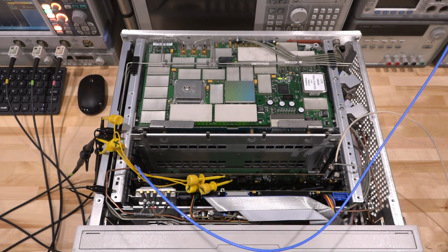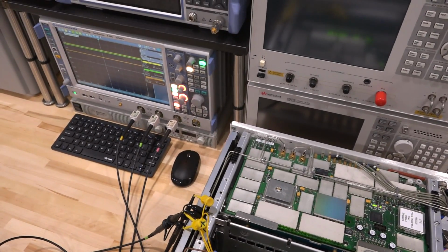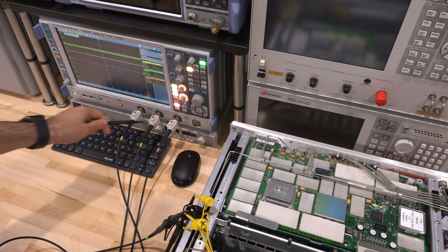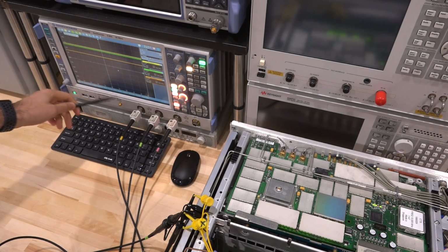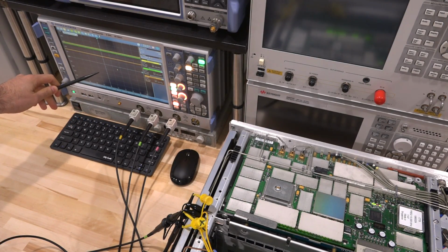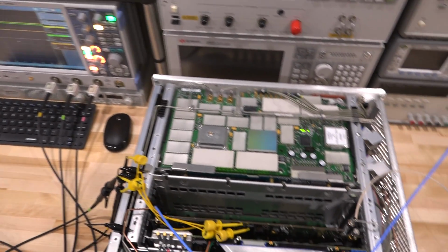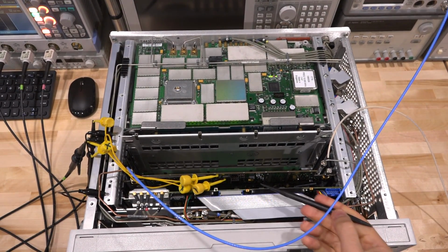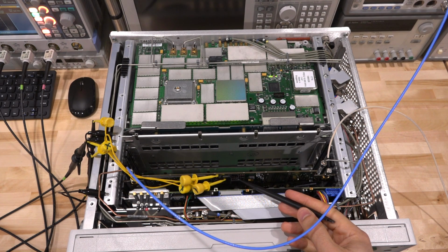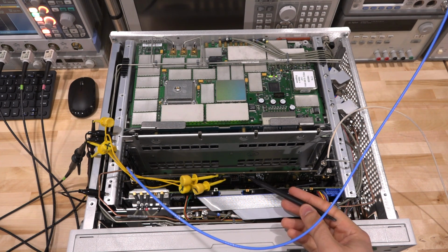So let me show you what is going on here. So here's the Rohde & Schwarz RTO. This is going to monitor the 3 analog voltages, and we can see them right now. They're all constant because the instrument is in 0 span. And interestingly enough, if you look at the instrument over here, you can see that it is locked. So I found out that the instrument is not unlocked across the entire frequency range, but only some of the frequency range. That's going to make things a little bit more difficult. If it never worked, it would be a lot easier to debug, but it means that it only works sometimes, and sometimes it doesn't work. So we have to find out in which frequency ranges it is non-operational.